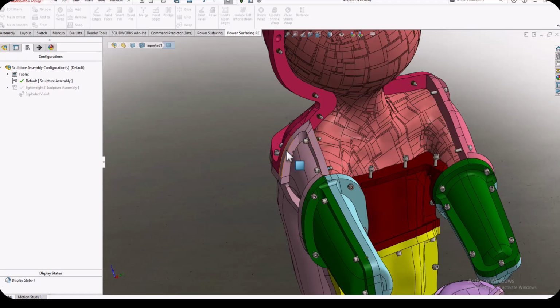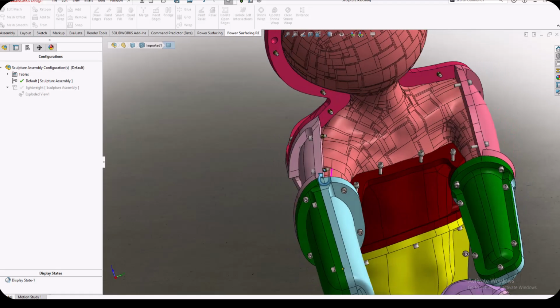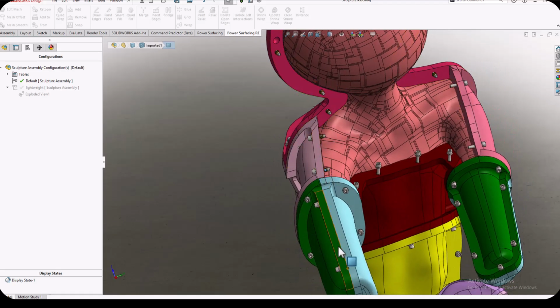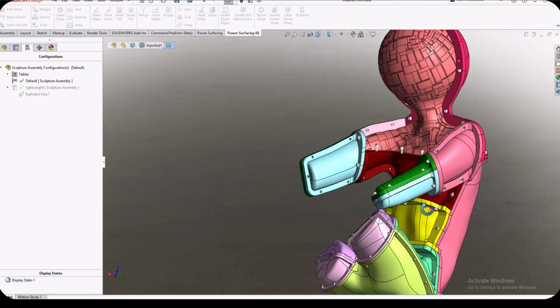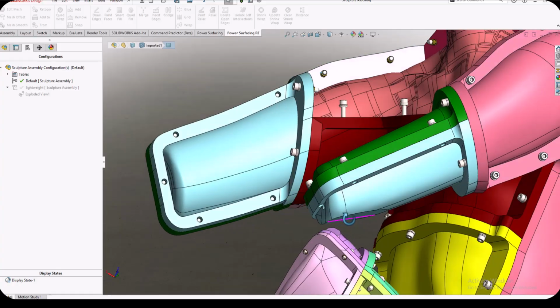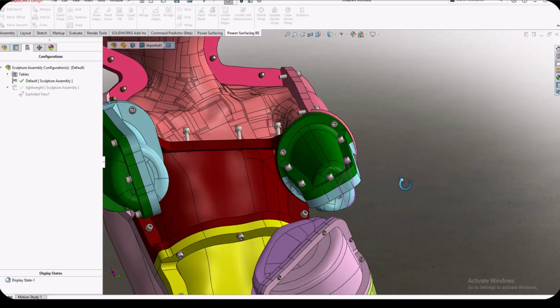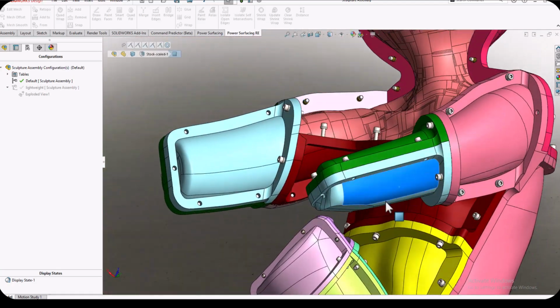The reason is that TPU is flexible. When you're removing the mold from the finished casting, that flexibility becomes a huge advantage. Although we carefully design the parting lines to minimize undercuts and make demolding easier, there are still a few areas where removing the mold can be challenging.